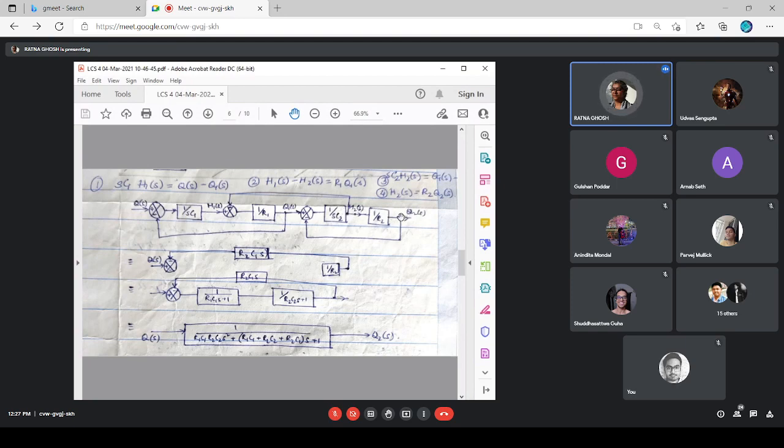This is a pick-off point, this is also a pick-off point, so it can be another pick-off point from this point itself. So three pick-offs from this node. It simplifies matters, which is why this was moved ahead of the block and this was moved after the block.